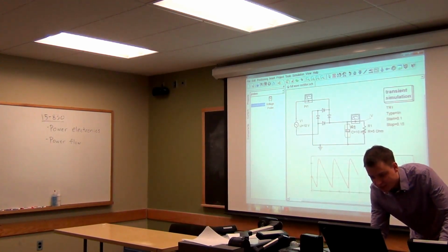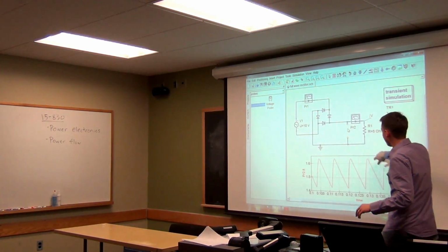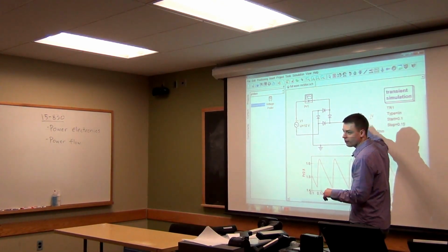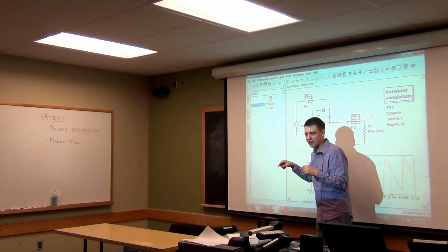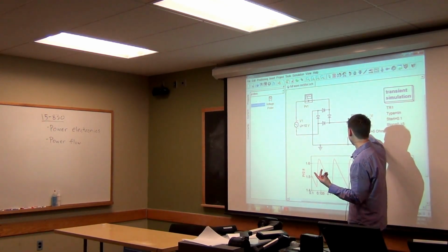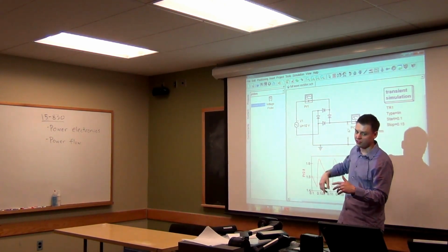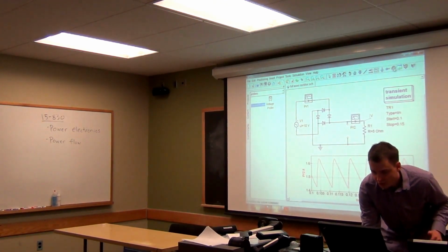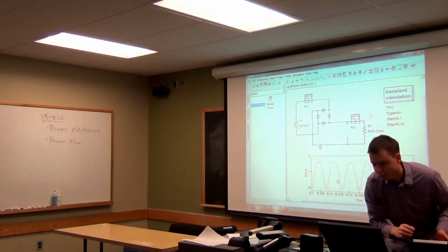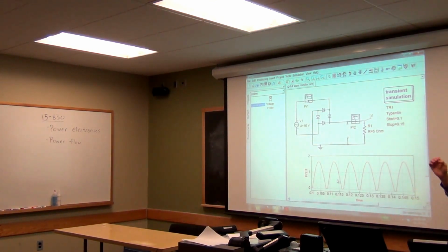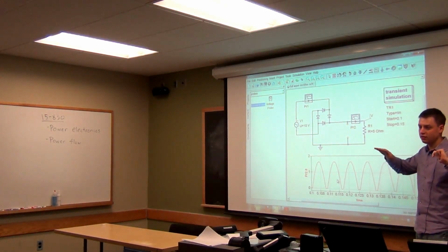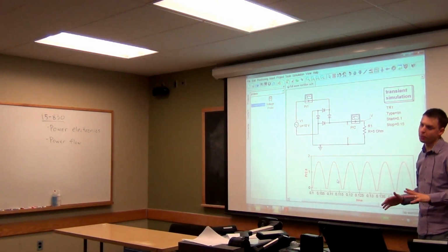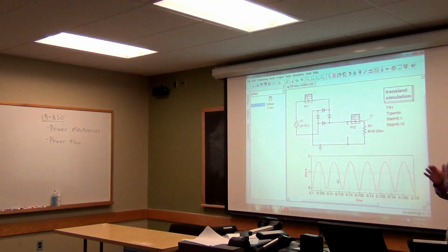So what we'll look at then is that, remember, what will happen here is you'll have a voltage here that is only the top half of these lines, right, of these sine waves. And so because this part here obeys Ohm's law, you'll see a current that looks exactly the same. So what you'll see is the current there looks just like the voltage there looked. The capacitor is essentially storing charge to maintain a constant DC voltage and therefore also DC current, approximately, subject to the little ripples.